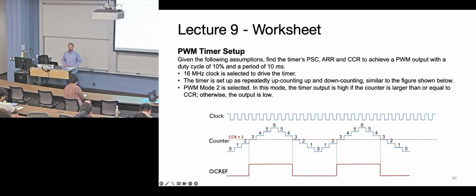Any other questions about this? Yeah. Going off what he said, that's what I attempted first too, and I originally started with a 1 kilohertz clock, and I had to go to 10 kilohertz for that reason. So is there a threshold? If our period is 10 milliseconds, do we need more than 10 divisions for that reason? Well, I think it's the peculiarities of whether you're actually at your ARR or not. If your duty cycle equals your ARR, then there's probably a problem. So by increasing the step sizes, you avoid that problem.